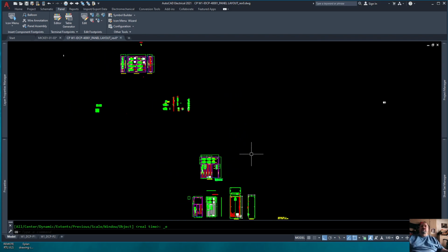So that is how you insert your wire duct and your Dinrail. It's not complicated, but it can save a lot of time because it's already blocked together. You set whatever length you want. It ends up being quite the time saver.